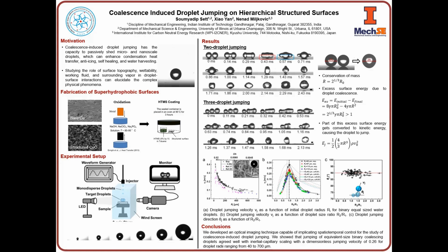To study droplet jumping, we interfaced a high-speed camera with a frequency-controlled piezoelectric droplet dispenser. By utilizing the piezoelectric dispenser to feed microscale droplets to a larger droplet at a prescribed frequency, we could create variable sized droplets on any surface by modulating the piezoelectric droplet adhesion frequency.